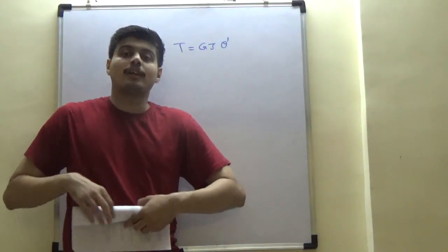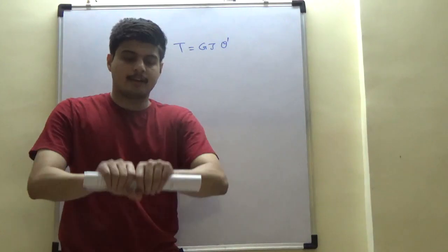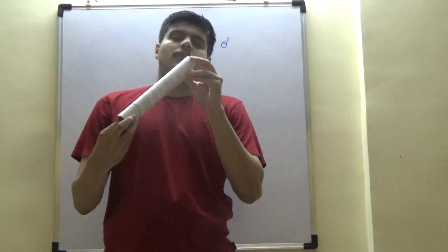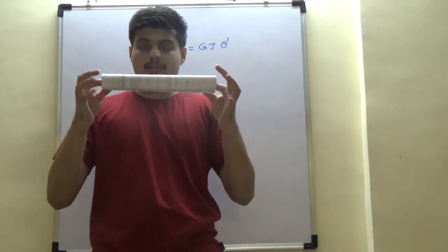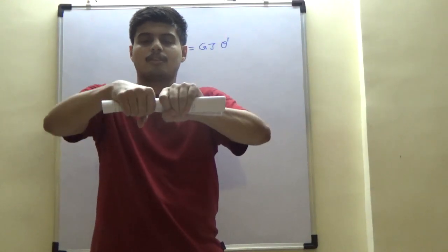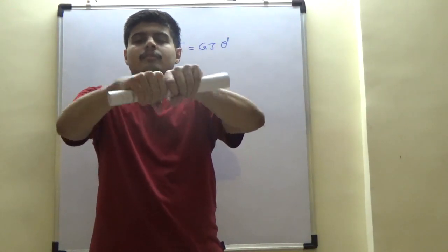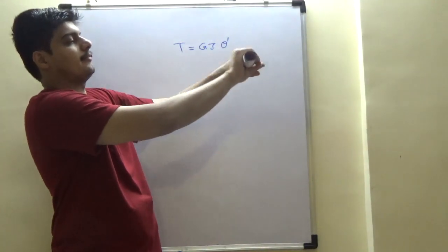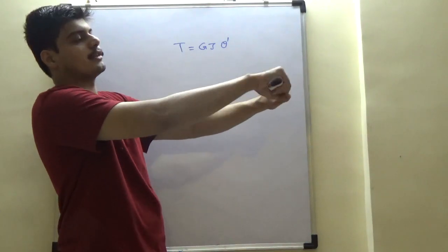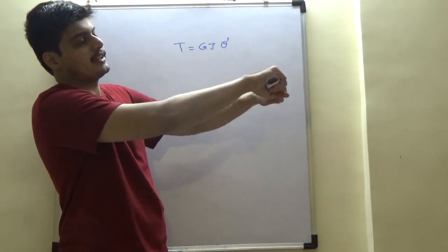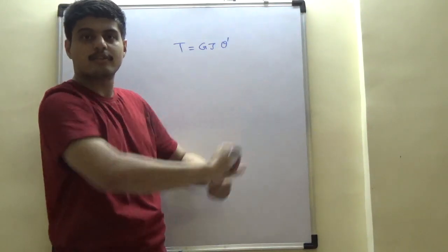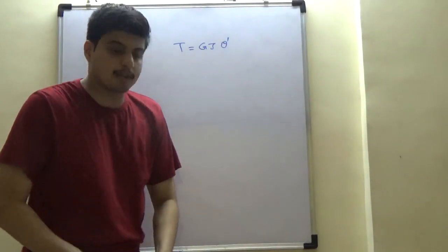This is one of the first qualitative tutorial problems you could consider. This sheet, which is open and not restrained from any warping, right? See how easy it is to bend this sheet. These are open sections, right? The moment I glue them, it becomes more complicated. You see how easy it is, right? The J of these open structures is extremely small. You can easily twist it.